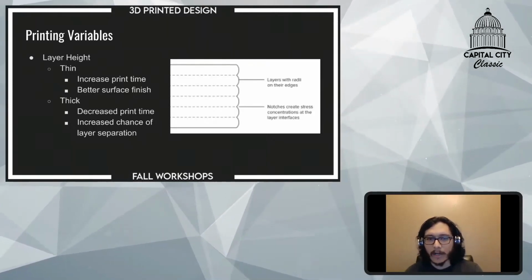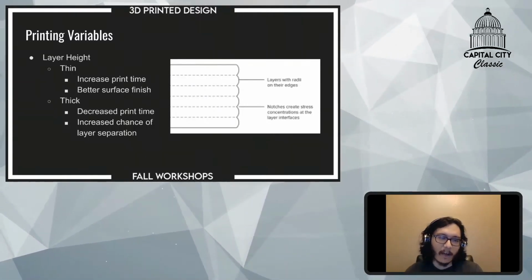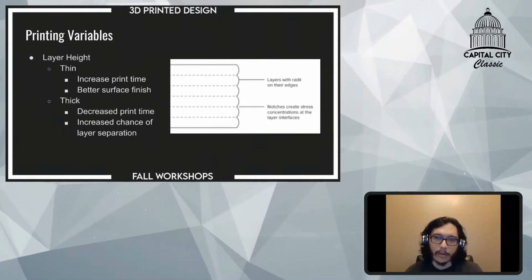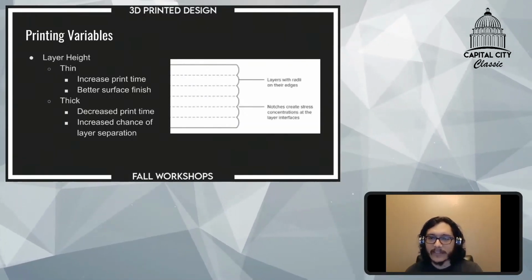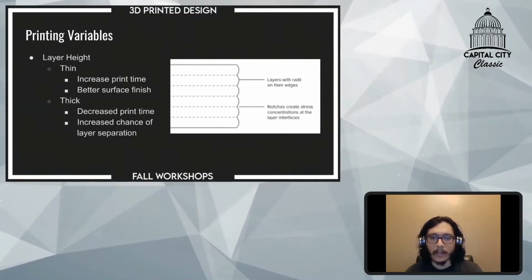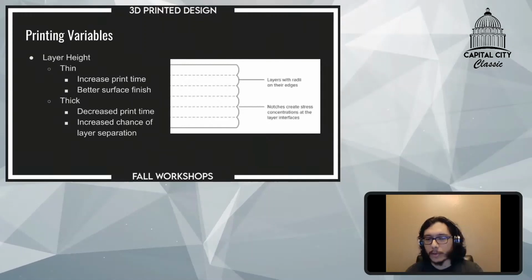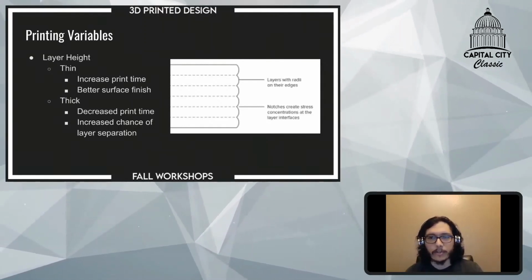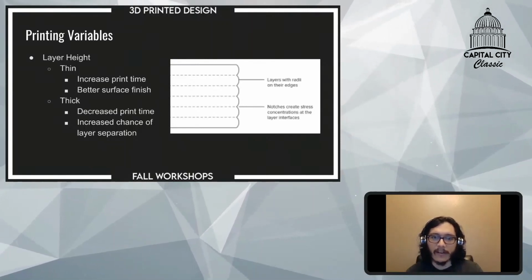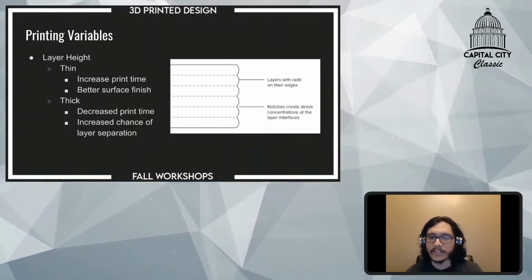I would not say that fast printing is useless, because although you are losing layer adhesion strength, you're actually gaining some strength because you're keeping the extruded plastic profile more intact. You're not having to squish it as you do with thin layers. So you do lose layer adhesion strength, but you do gain some strength in the opposite direction of your layers, in the direction of your fibers.